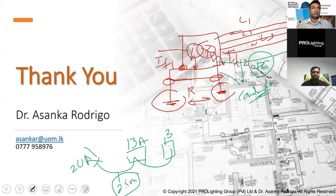In the TN arrangement, your earthing is anyway there. Even for the TT arrangement, that requirement came because of the earth loop impedance, which can create a higher potential rise in the earthing system. But that problem is not there for a TN system. In a TN system, we are not talking about what should be our earth electrode resistance value. Nothing is needed because your electrical earthing system is connected to the source earthing system. So if there is an earth fault, there is a low impedance path. That impedance path will not raise the earthing system voltage. Because of that, you have higher protection, higher safety in a TN system than the TT system.